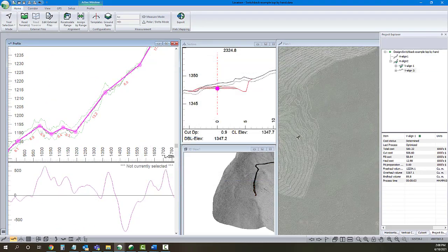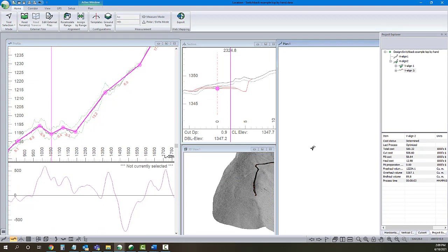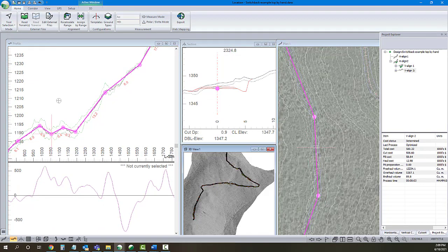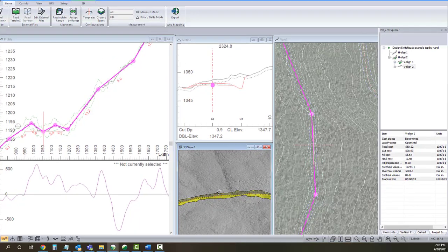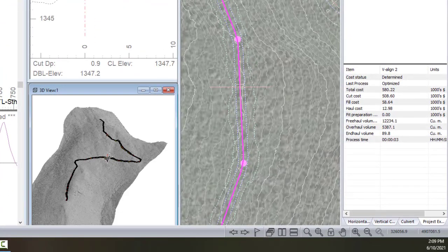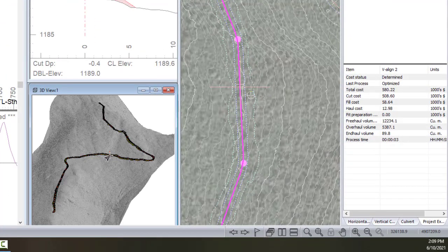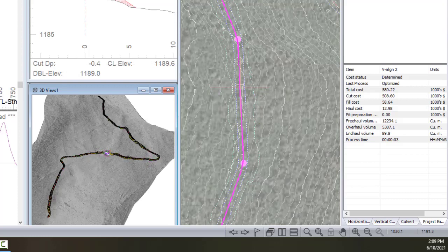So before we optimize or change anything, I'll just touch on why I'm doing that. So here is one of my control points. I'm crossing the top end of a fan. I want to have it so if I lose my crossing, I want it to funnel the flow over my road at that location. So I don't want to alter the fan. So that's just an example of where we'll use the optimizer, and the user will still have as much control as they want.